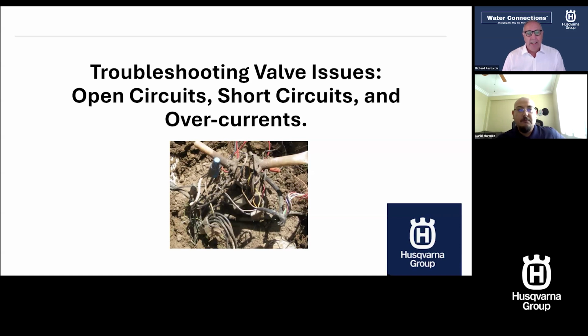And it does that by sending electrical current? Your standard controller runs off a 24-volt system, and it'll activate a station, sending voltage down a wire path to a solenoid electromagnet, which opens up your valve, creating a pressure differential between the diaphragm, opening up and allowing the water through to your stations.